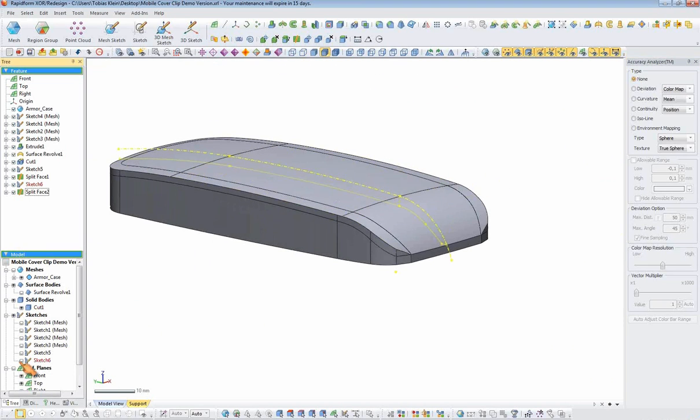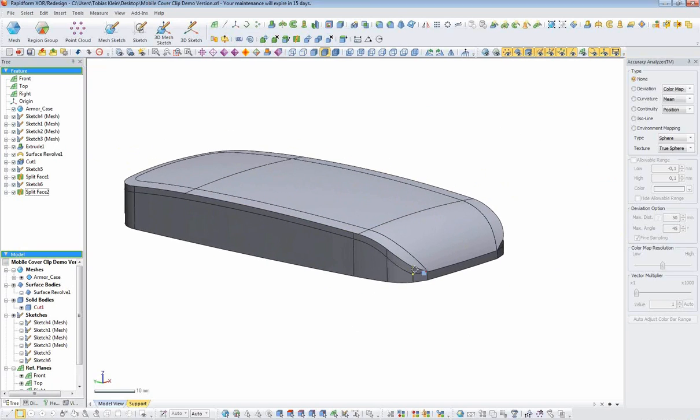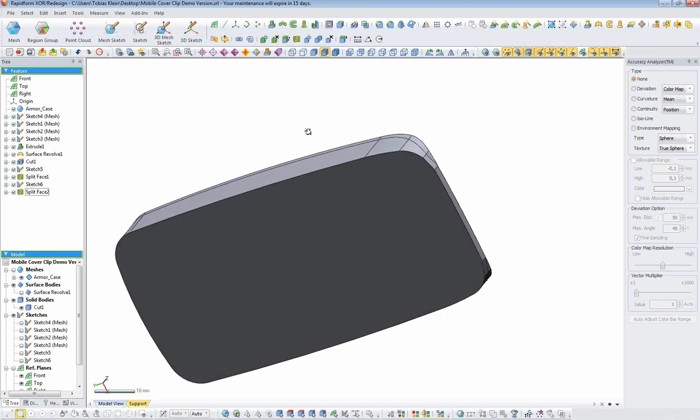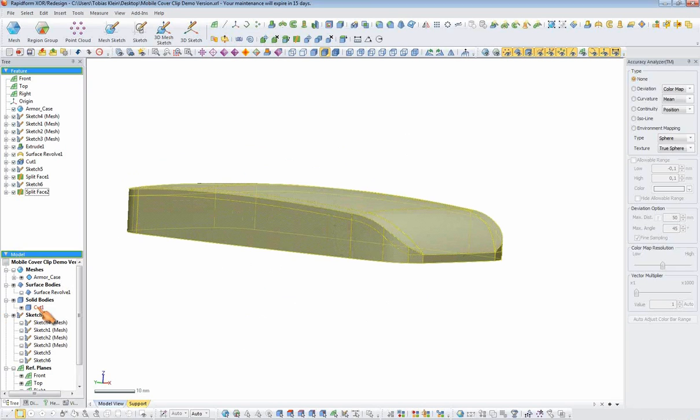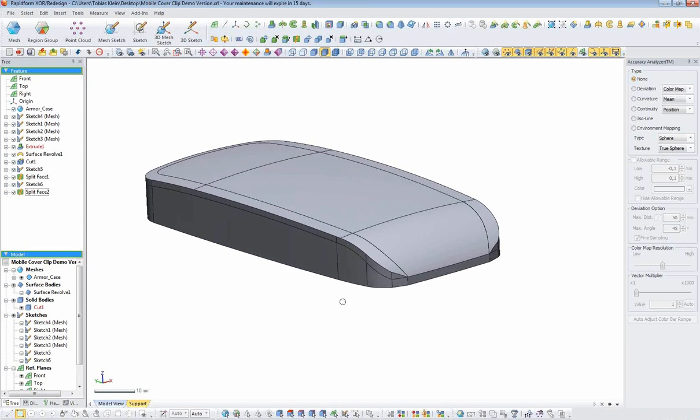And then the next step would be replacing those faces by loft surface which is running around here. So I can delete that face. Actually we are now modeling still a solid, but in XOR we don't separate between surface and solid, so every closed surface set is automatically a solid. And if I delete some surfaces from that surface set, we get an open solid, so it's a surface.